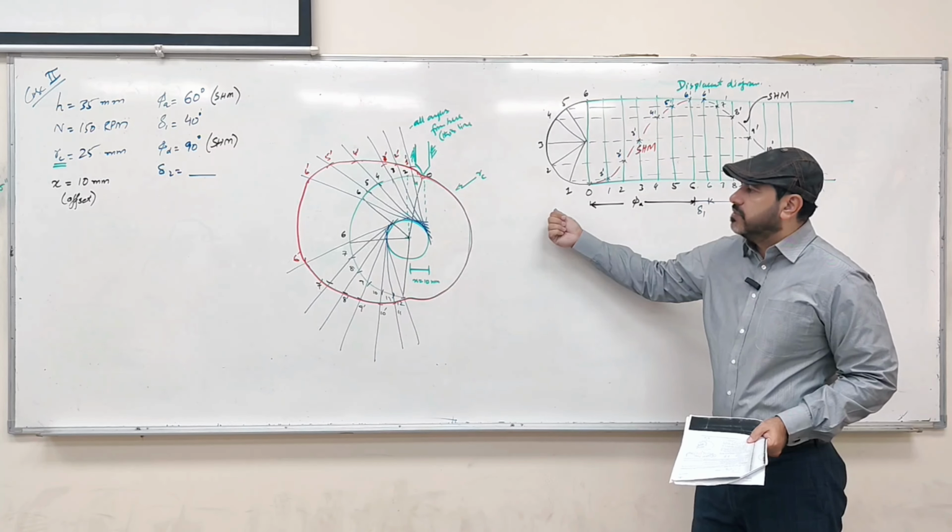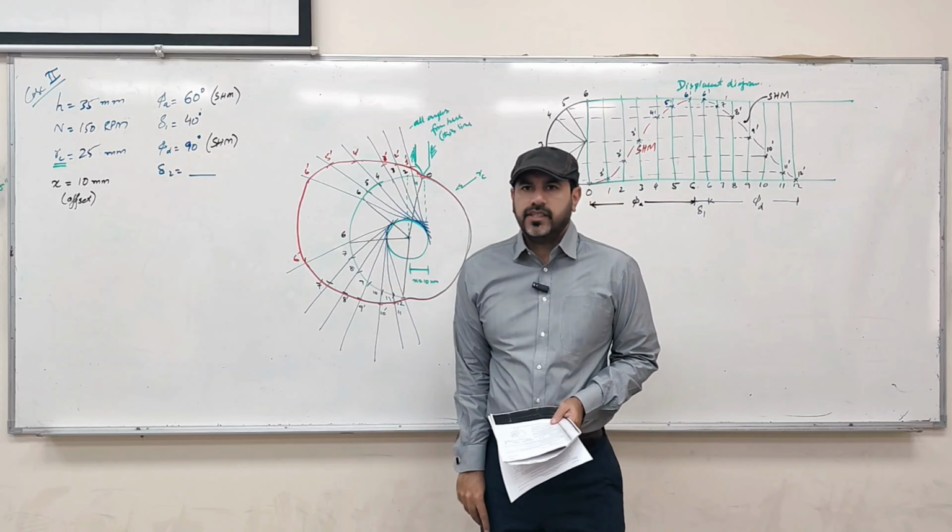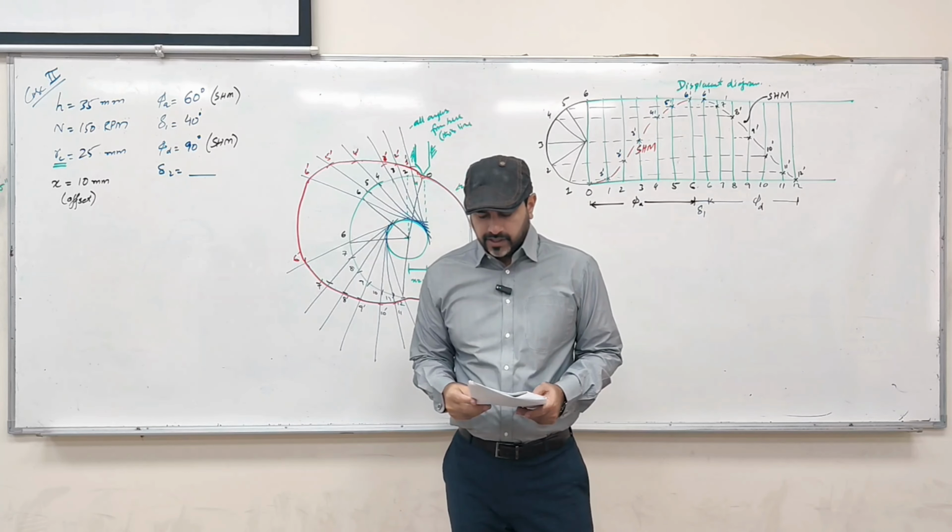But if you want to make more points so that you can join it easily, you can draw another semicircle on the other side and use it as a reference. Here, what we did is we have the same number of divisions, we divide it into 6 parts, and then extend them again, tangent, point, tangent, point, tangent. Then come over here, 7, 8, 9, take the reference of this, okay? So you take the proper references, draw them over here, back here, and this red color curve is the shape of the profile.